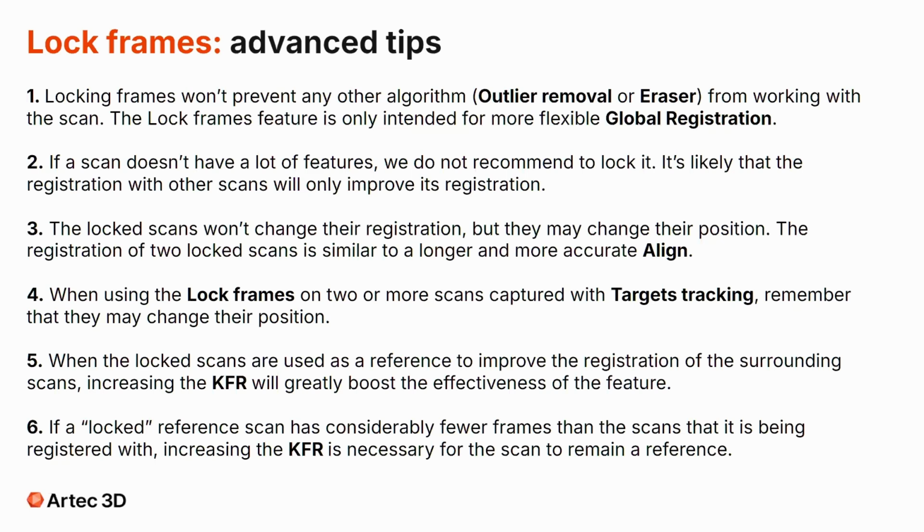It is also important to remember that locked scans can still move as a single unit to find a better fit. The internal frames are frozen, but their global position is not. Finally, if you're using a small high accuracy scan as a reference for a much larger dataset, you must increase the keyframe ratio, KFR. This forces the software to treat that reference scan with the priority it deserves, ensuring it remains the anchor for the rest of your project.